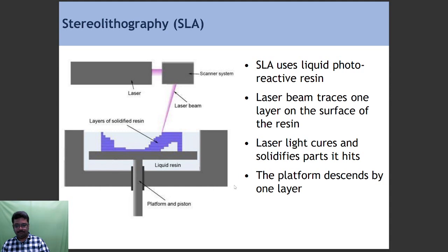Once we dip the material inside a liquid resin or liquid binder, we can pass some heat via laser, and it can stick. The technology of 3D printing is the same, where we need to heat the material and melt it, then it sticks. Here we dip the material into a resin, and then we can do all the things. It is the same simple setup where we can prepare huge parts through stereolithography. That is the only difference here.